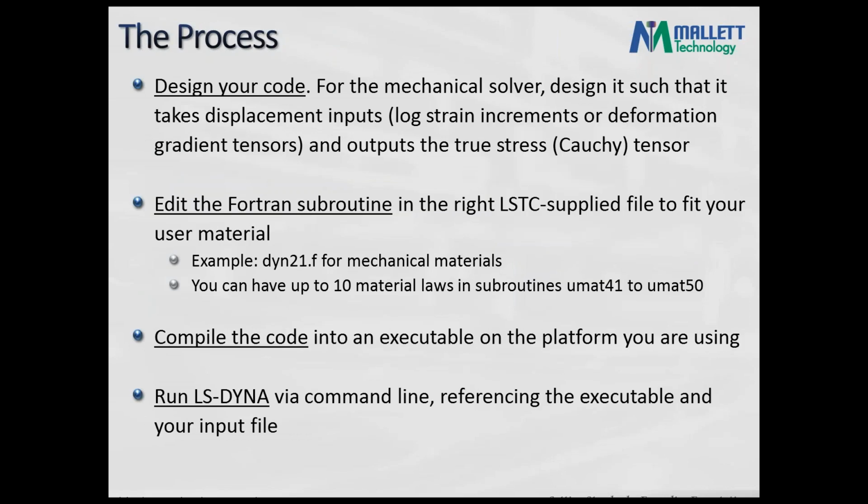So now that you have all those things, the first thing you need to do is design your code. For your mechanical material, you need to be able to take your displacement inputs and transform them into your stress outputs. For those deeply in tune with solid mechanics, you need to be able to take either log strain increments or your deformation gradient and output a true stress, or Cauchy tensor.